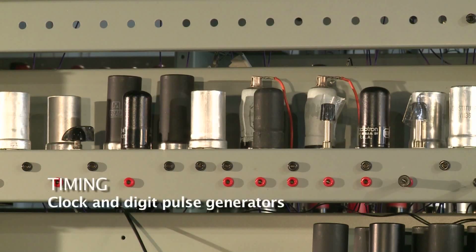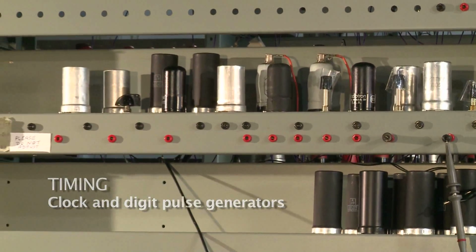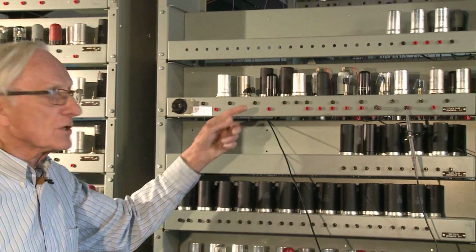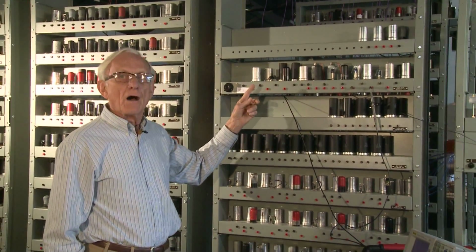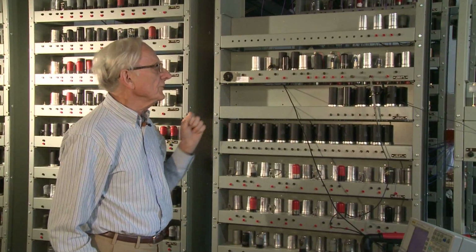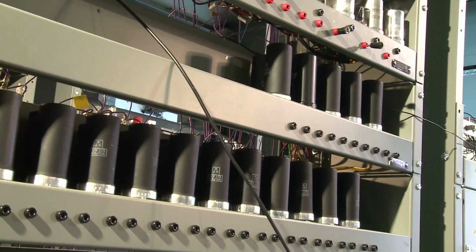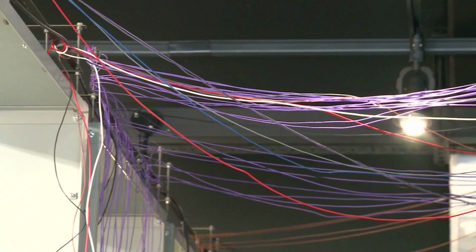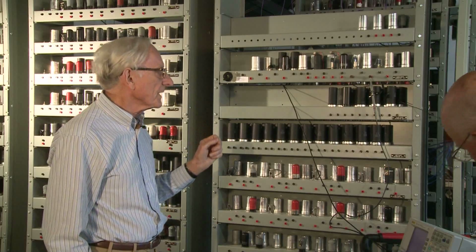Central to any computer is a time system, a central source of clock pulses, which are provided on this machine by this chassis here, which provides clock pulses at roughly 500,000 per second. The chassis we're now looking at are the powerful cathode followers which drive signals over the machine. And those clock pulses are distributed to synchronize the way everything works.